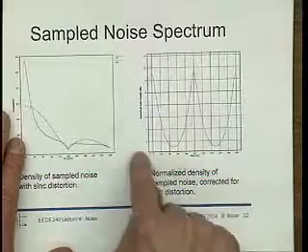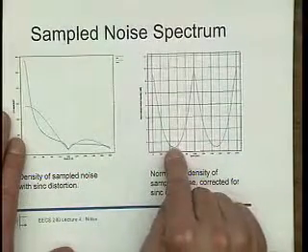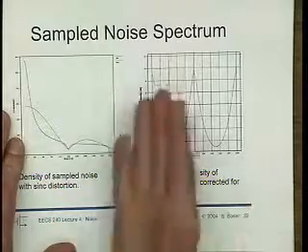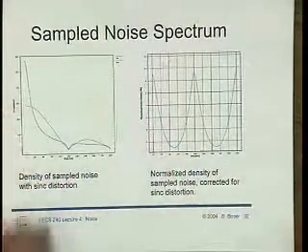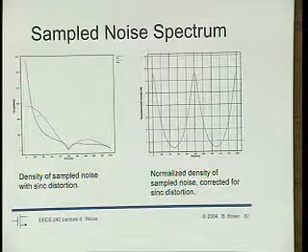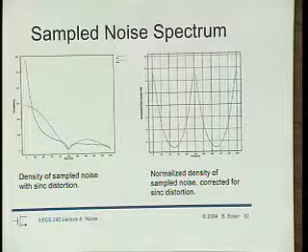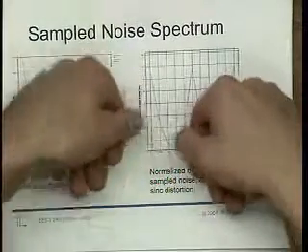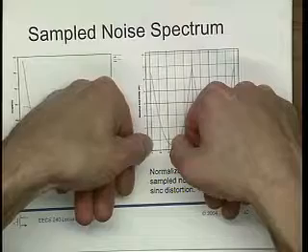Here is a linear scale. It's going to be a low pass. Here is Fs over 2. And then it's going to be just a mirror, again, to Fs, and from then on it's just going to mirror around that. Now, we know that the power of this noise is going to be equal to kT on C. And the noise power is integrated from 0 to Fs over 2, right?